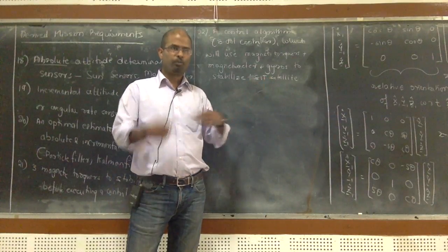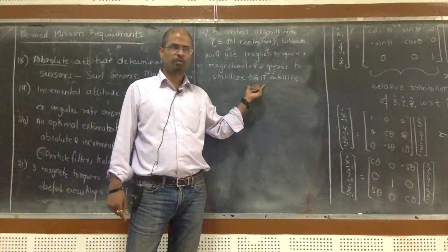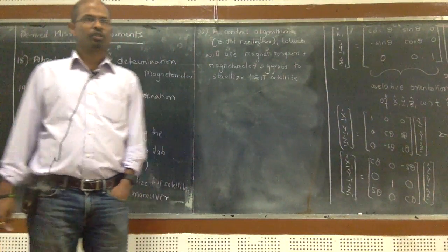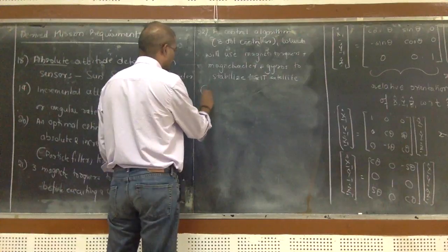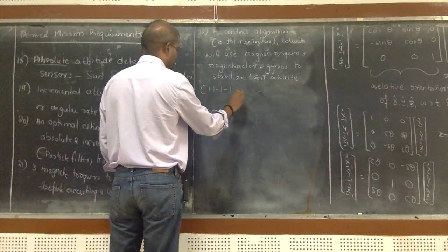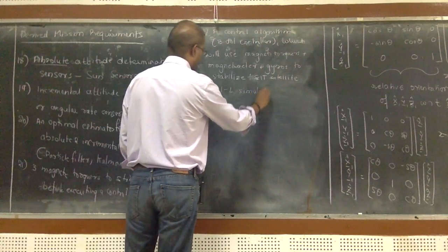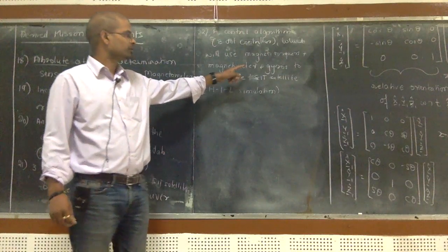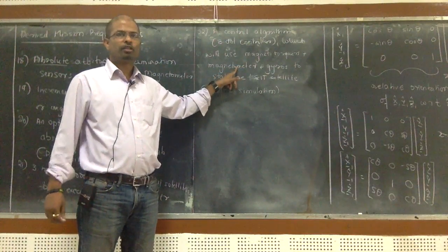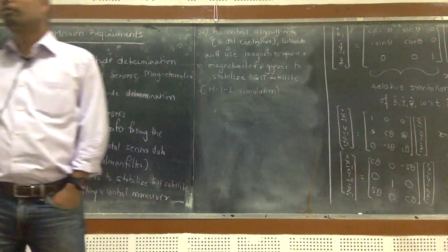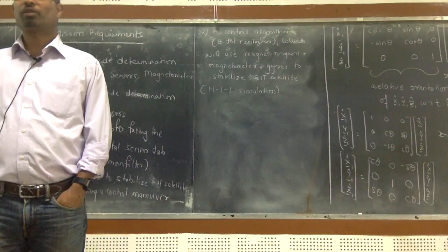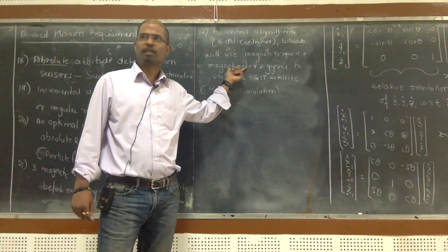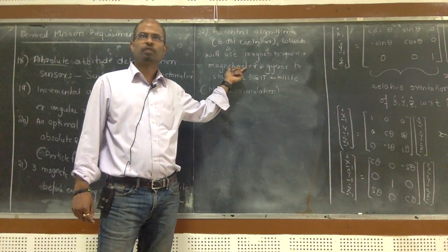The students will build their own torquers, buy a magnetometer, gyros, and then do some MATLAB simulations. So this is a hardware in the loop problem. This is a candidate for hardware in the loop simulation. How is it a hardware in the loop simulation? Is any magnetometer going to give you perfect measurements? No magnetometer is going to give you perfect measurements, right? So you need to include some noise characteristics or bias characteristics. Noise model, bias model, right?